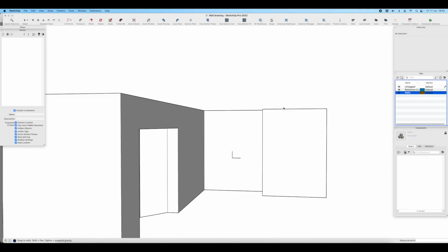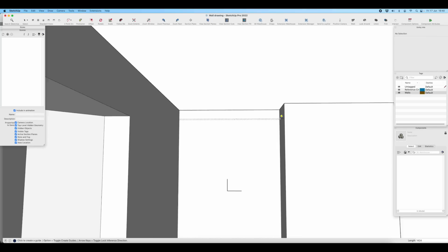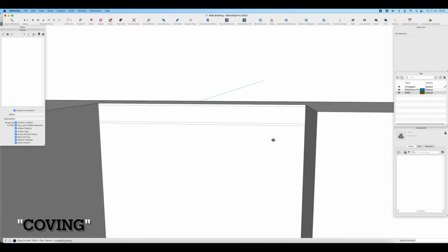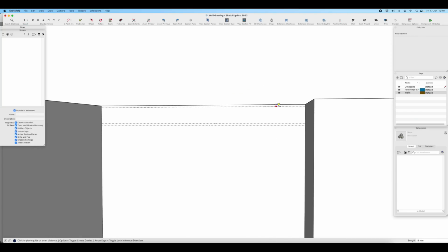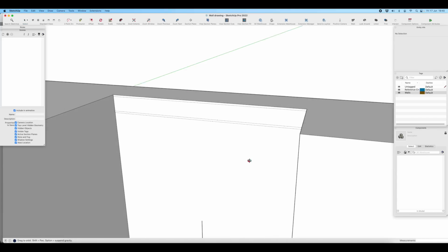So we've got our reference cross there. We need to sort this outer level ceiling out. So on the left hand side we had 1442, and on the right we had 1424, and then we had 180mm of cornice. So the room is actually out of level by 18mm across this section where the wardrobe is.